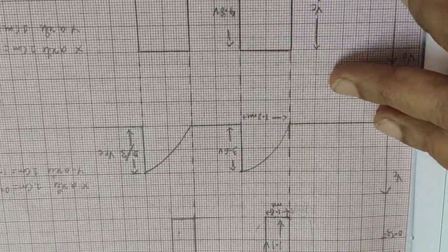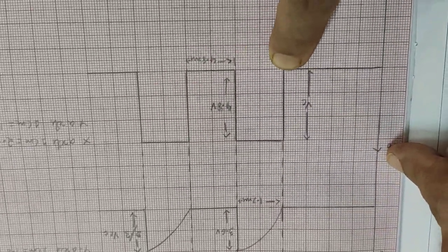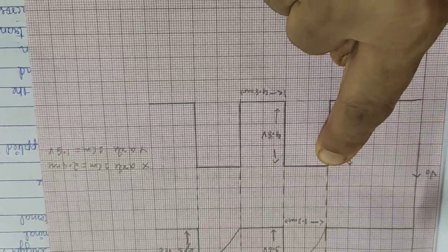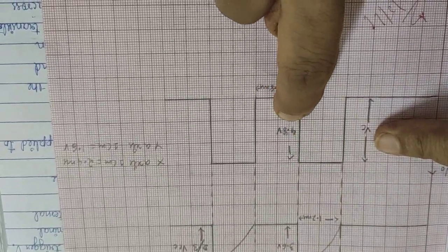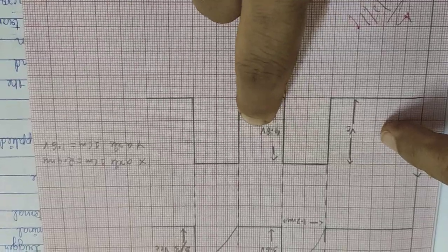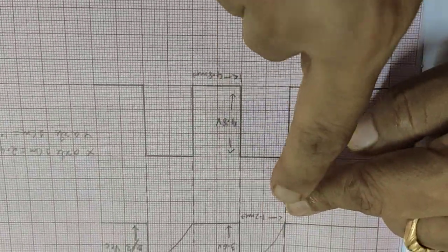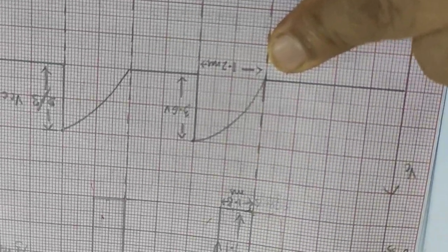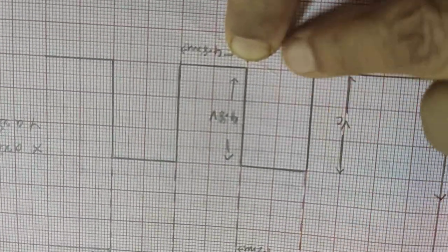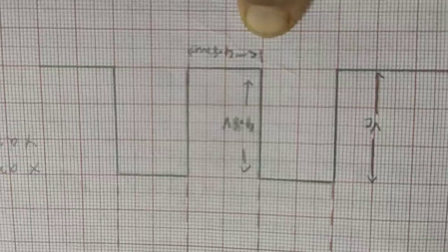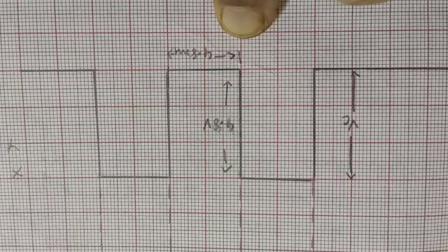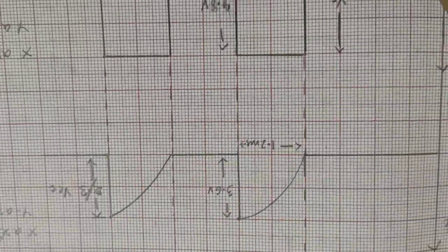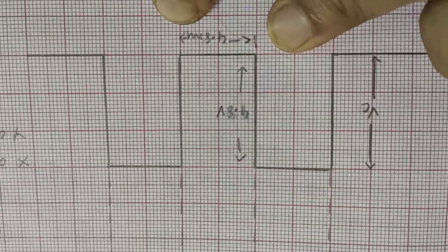As it is getting charged, we can see the output is also rising high. It has to be equal to VCC, which is 5 volts, but due to experimental errors we are getting 4.8 volts. The charging timing is 1.2 milliseconds, and TP is also 1.2 milliseconds. Within the experimental errors, we have got the timing. Then this is Td, the delay time, which is equal to 4.1 milliseconds.